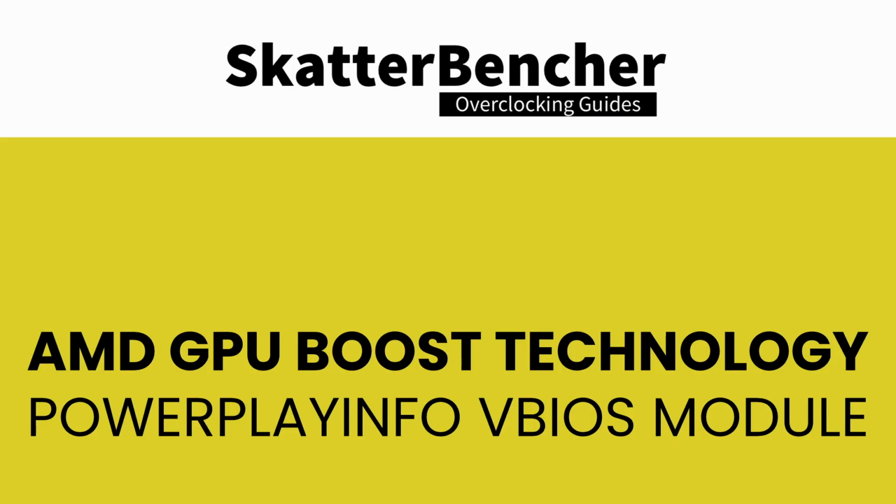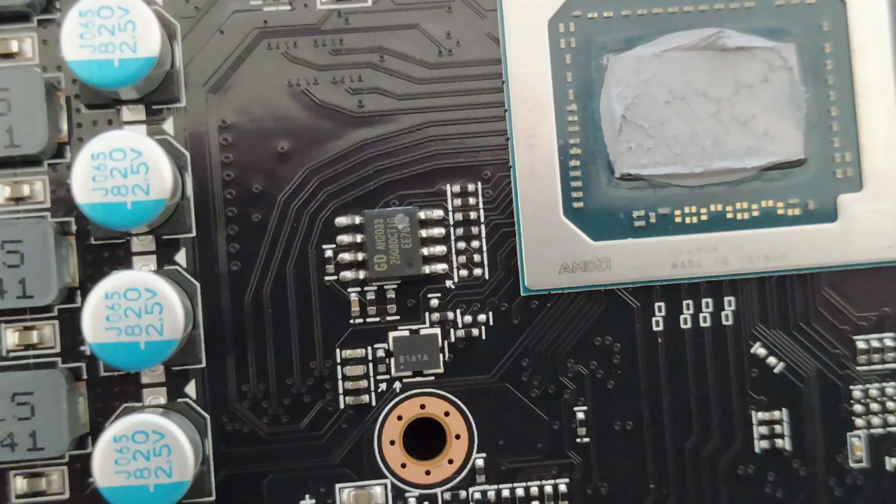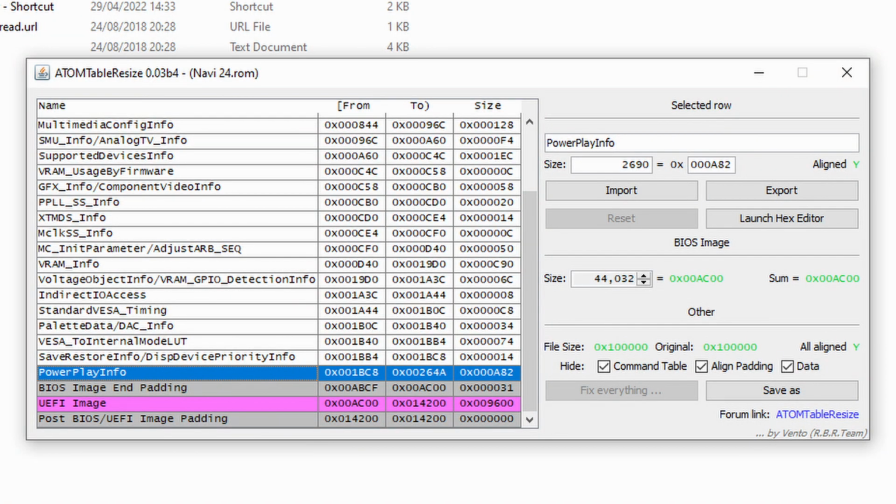The last topic we must tackle before moving forward is the VBIOS. The VBIOS is essentially the BIOS on the graphics card, and it contains all the information required to boot up your graphics card. The VBIOS often contains multiple modules which provide information about the graphics card or define certain specifications. On AMD graphics cards, a specific module called PowerPlay Info contains all information related to the performance specification, such as the frequency and voltage for each DPM state, power and thermal limits, and fan speed configuration.